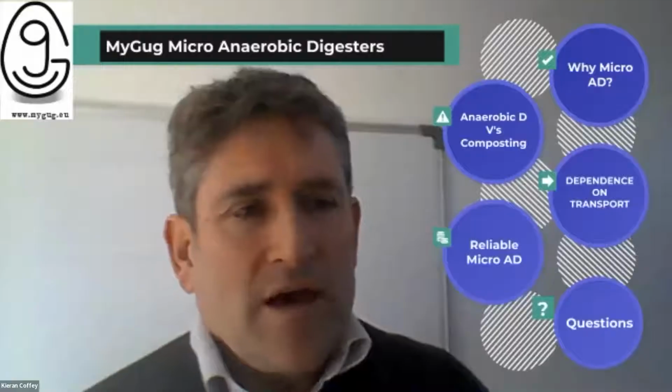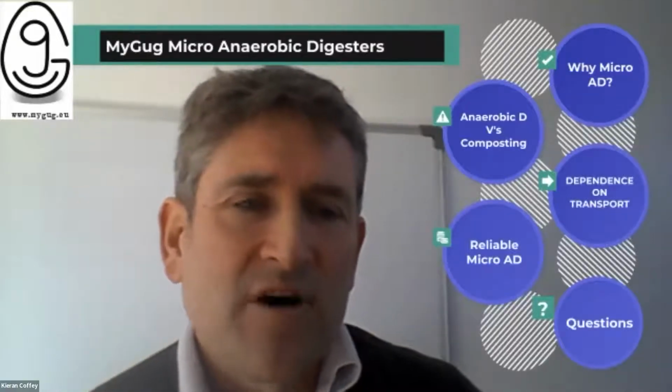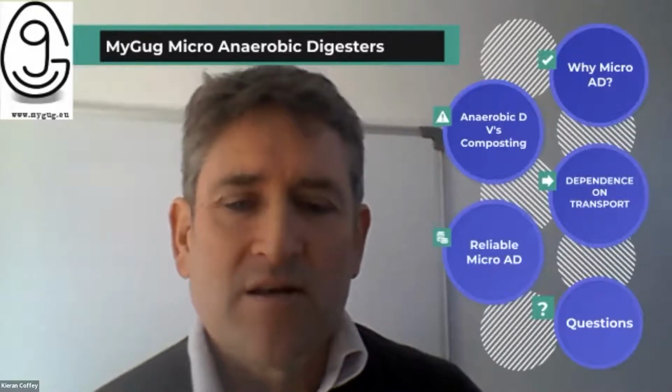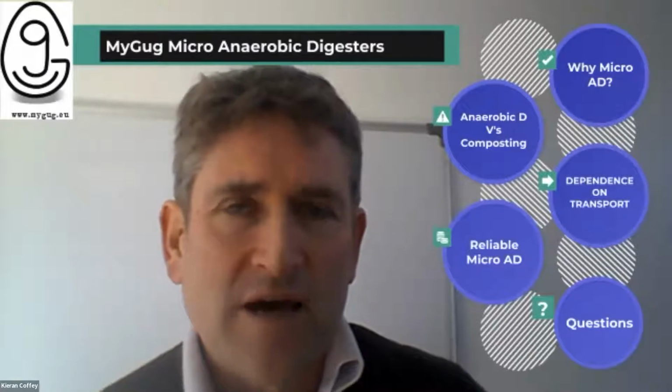Question from Donal. Good to hear from you, Donal, too. Would an LPG or natural gas cooker need conversion? As I assume the gas from this would be of a lower CV value, so calorific value. Yeah, the biogas is usually between about 55 and 65% methane. So you need more gas to operate a standard gas hob.